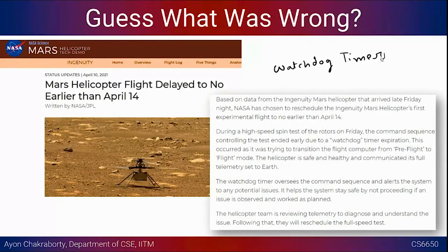So every time, the way it is implemented, once you execute a certain code fragment, you are supposed to go and do something with the watchdog timer. What we call feeding the dog. We give an analogy that the dog is watching your system running. So you execute something, and after that you go and signal that you are present and executing that thing. Go and report that to the watchdog timer, so it knows that whatever you are doing is expected.